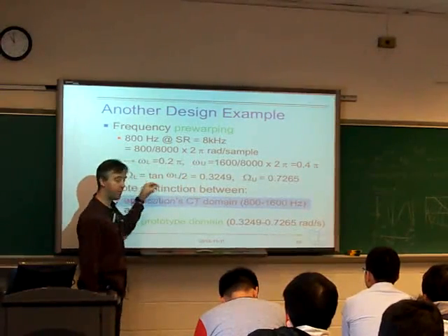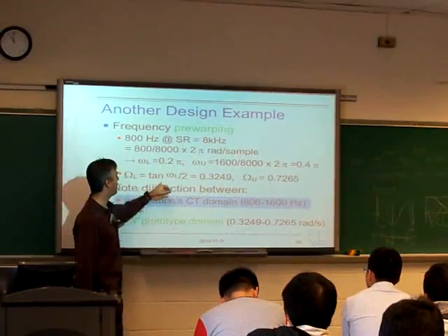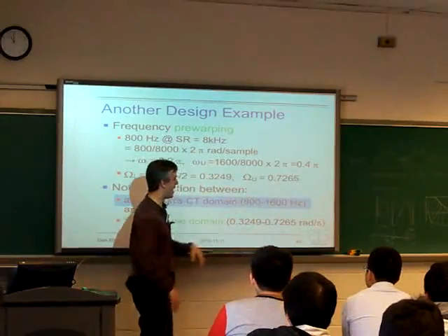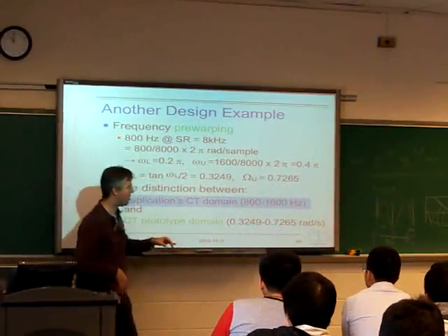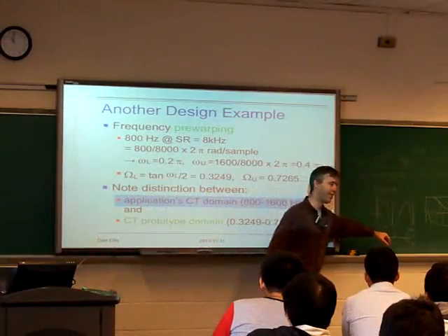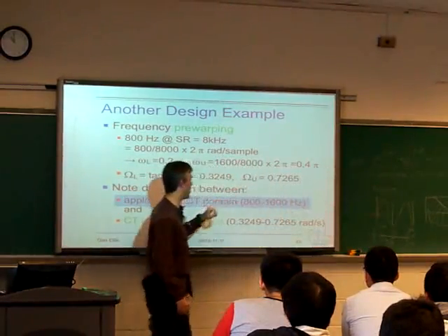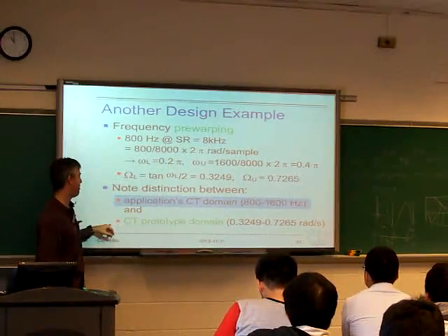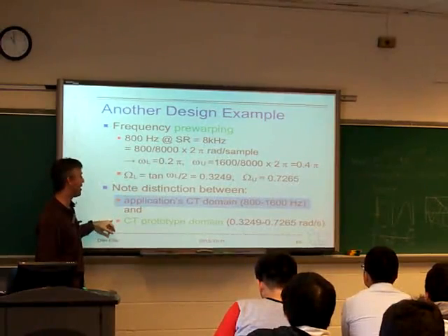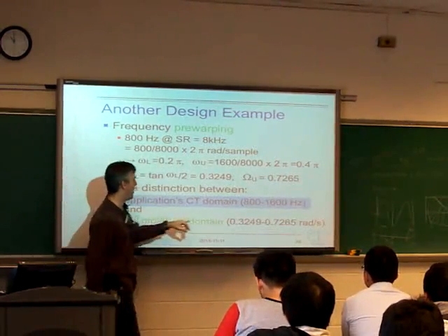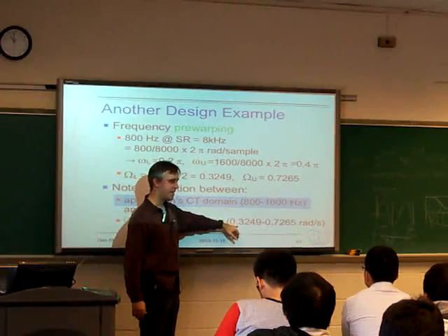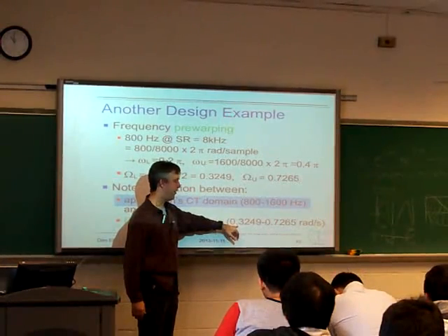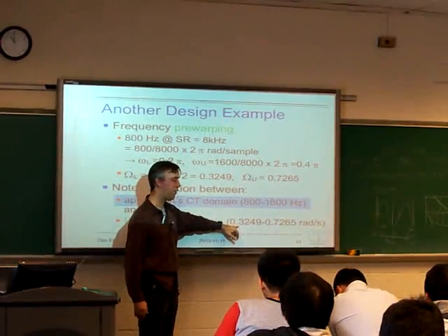And when we do the inverse bilinear pre-warping, we get these frequencies in radians per second, which of course are not at all these frequencies in radians per second. They're different. They're just in this design domain. We end up with totally different values here, right? 0.3 radians per second is like a tenth of a cycle every second, so it's like 0.1 hertz.